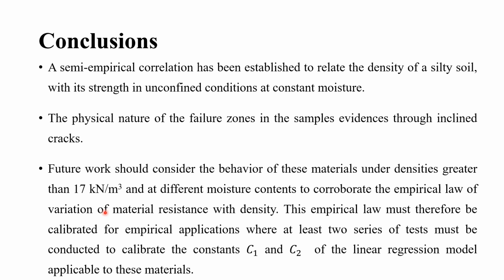More important is to use several types of soils and put them in very different conditions, in order to confirm that the empirical relationship that is being proposed can be used, that is, that we only need two constants in order to establish a correlation between the density and the simple compressive strength of the material in order to predict the mechanical behavior of the material under different densities.